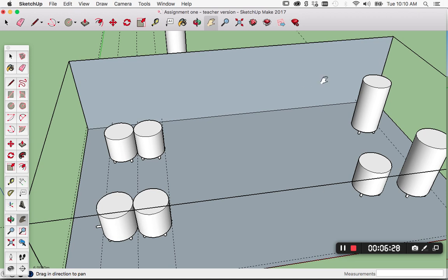So how high are these tanks? These tanks are 4 meters. So the total head would be around 4 meters, because we're taking it from the base of this tank up above this tank and then dropping it in. So the maximum static head for this transfer really won't change.